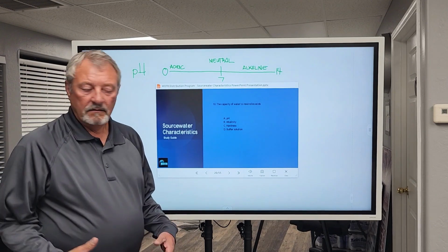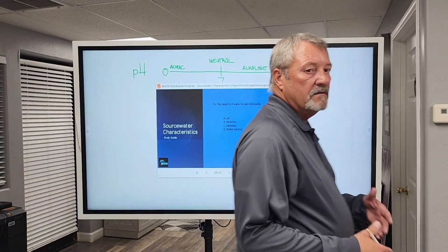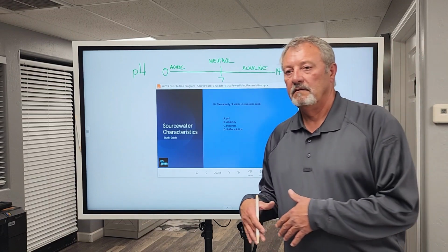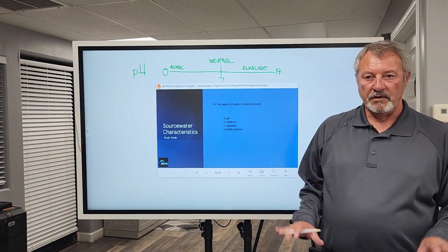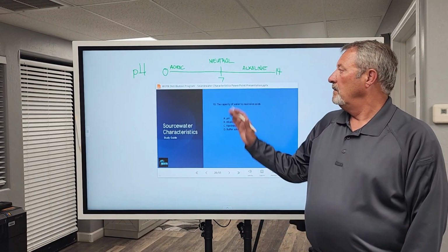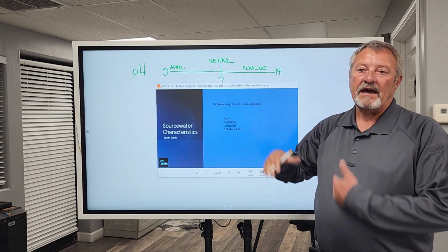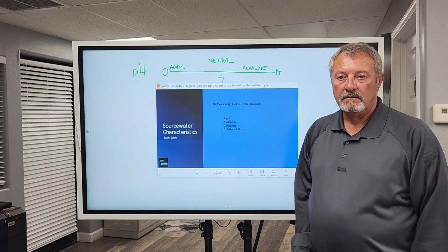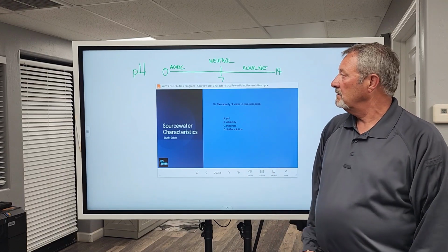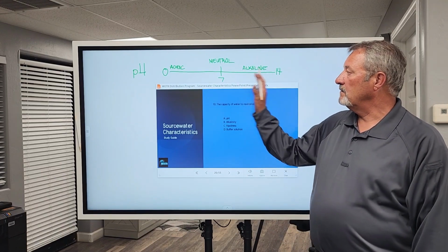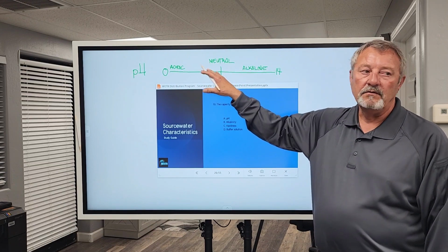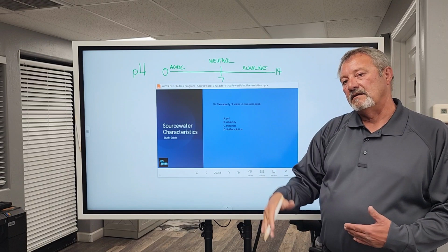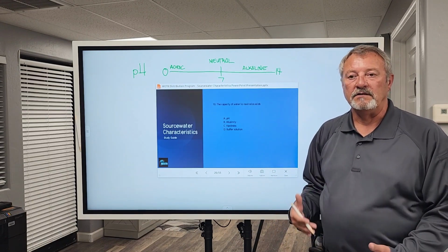Treating water. If our source water is at 7, that's perfect. It's the best water to treat, least expensive on a pH scale. The more acidic it is, the more alkaline we have to add to the water so that we can adequately treat the water, depending on the treatment process. There are times when we do want acidic water, there are times when we do want alkaline water, but it takes adding chemicals to change the pH.